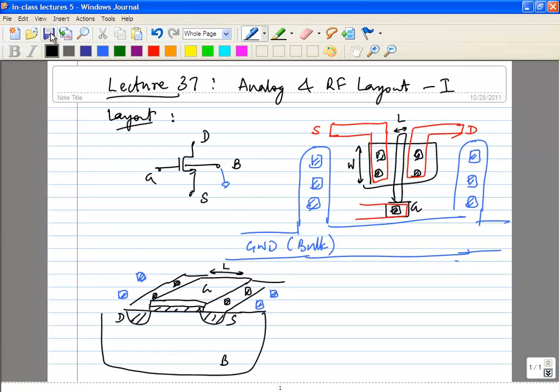So typically the way it works is, before the layout engineer starts working on it, the designer needs to design the circuit such that it can be laid out directly. Okay, preferably giving some information on the signal flow, because the layout engineer will typically not know a lot about the design of the circuit itself. He won't know which lines are critical. So what you will have to do as a designer is do what is called a floor plan.